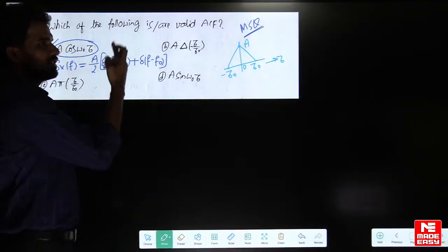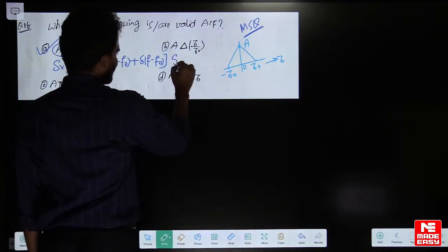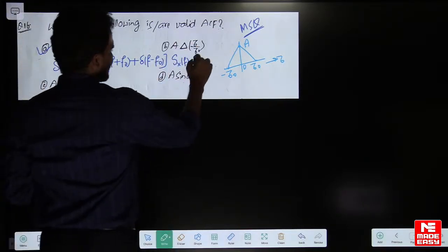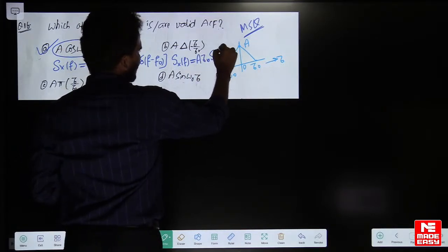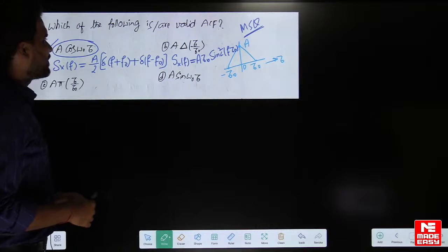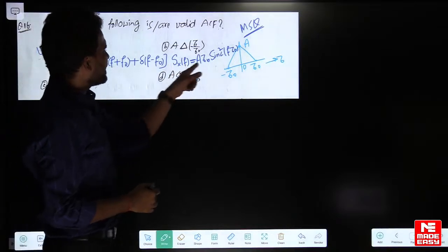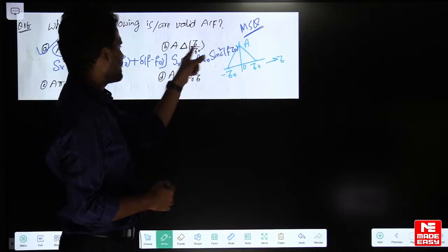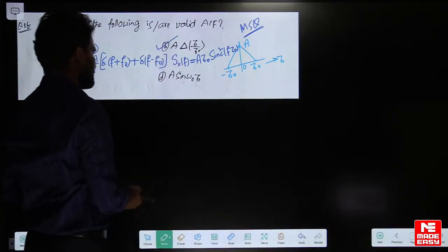Okay, and one more thing: if you see the PSD for this, the Fourier transformation of this, what is it? I think you know this, it is a standard result: A tau naught times sinc square of f tau naught. This is the Fourier transformation. This is the PSD. The Fourier transformation of ACF will give you PSD. Okay, so this PSD you can see takes only positive values. Sinc square takes only positive values, and this is also an even function. PSD is also even. So this is a valid PSD, so this is also a valid ACF, I can say.